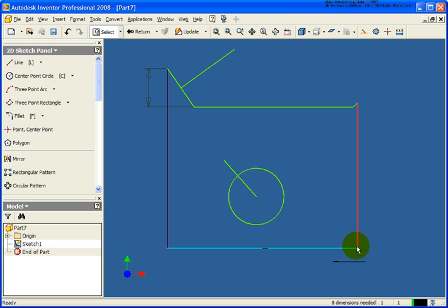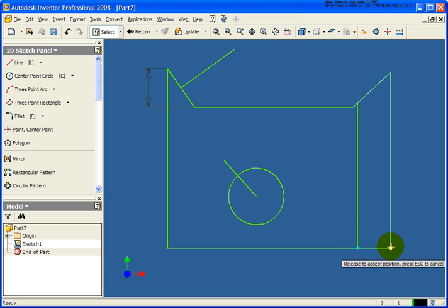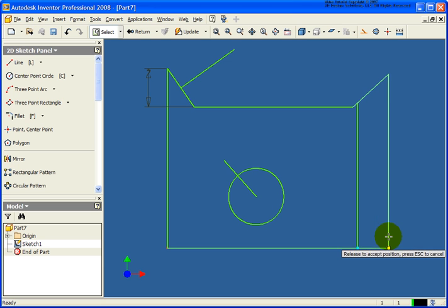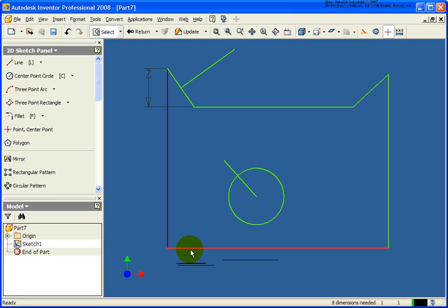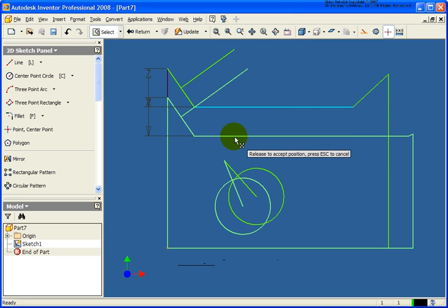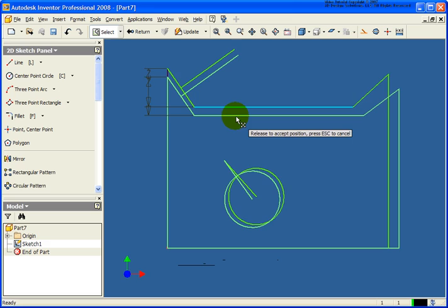Of course, I can still drag the opposite side, make the line longer or shorter, but it is locked down horizontally, and in this case probably perpendicular as well to that. So keep in mind that you can only drag objects that are under constrained.